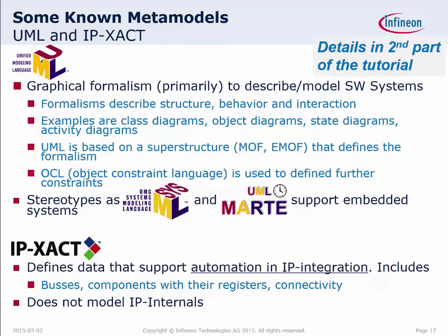IP-XACT, most of you have heard about IP-XACT. It defines, let's say, the data core models for specification reuse and exchange. For example, it defines how registers are structured, how top-level connectivity is structured, how transaction-level modeling connectivity is structured, and how interfaces are structured. It's an industry standard.